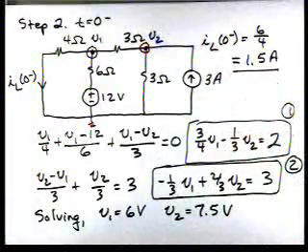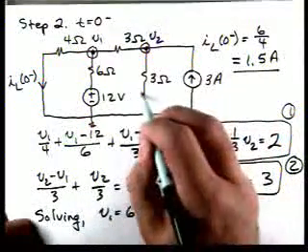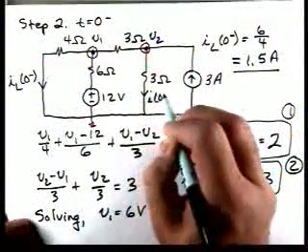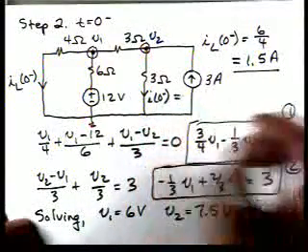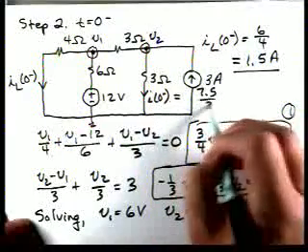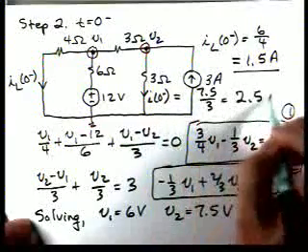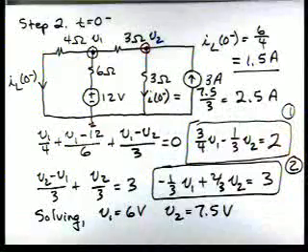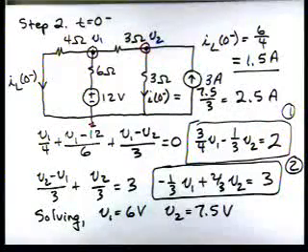If we really wanted to, we could also solve for i0 minus, and that would be 7.5 over 3, or 2.5 amps. We really don't need that. We'll use it later on if we decide to plot it. But now we've solved for the initial condition on our inductor. We know, for instance, that the inductor current is continuous through the switching operation.